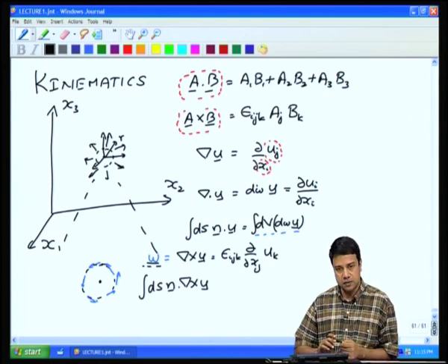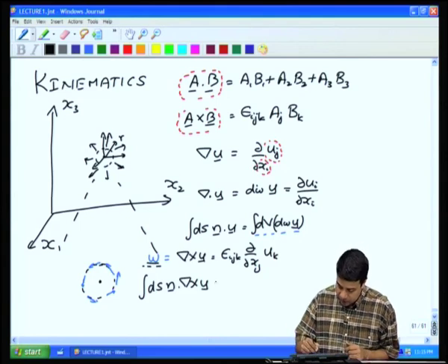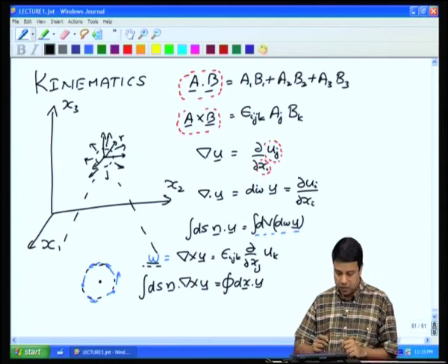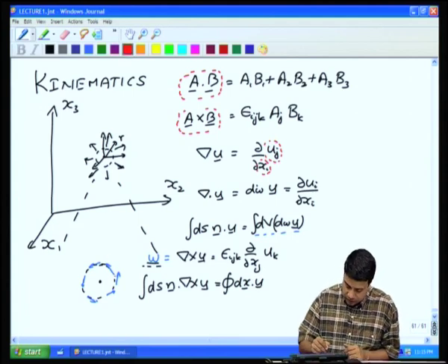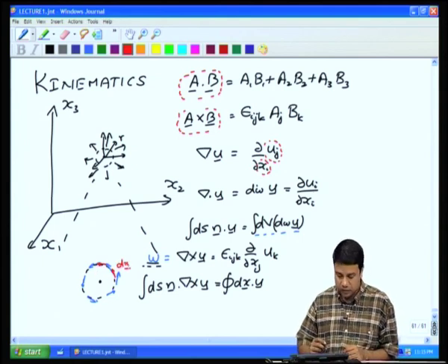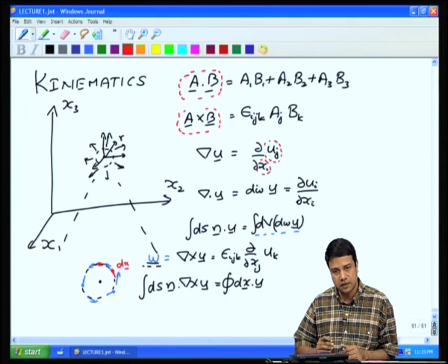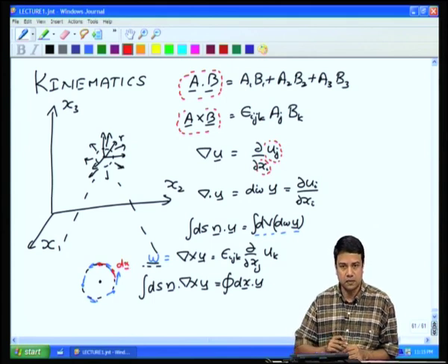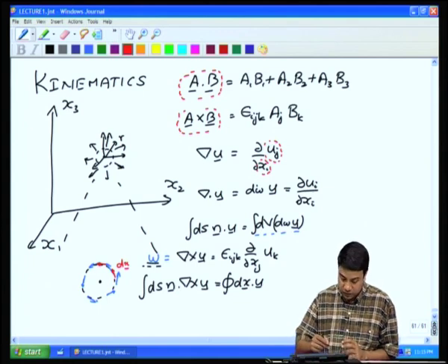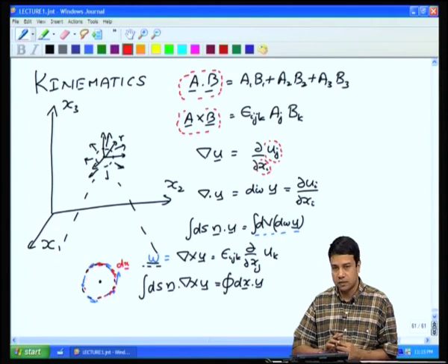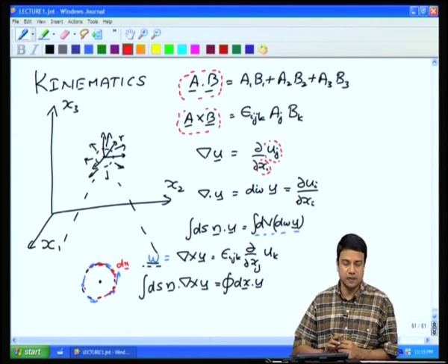and this integral of the unit normal dotted with del cross u over any surface is equal to the line integral of dx dot u. So, I take this little differential element on the surface, that is dx vector, and dot it with the velocity vector at each point, and then take the integral over the entire contour. That is equal to n dot del cross u over any surface for which this contour is the perimeter. Okay. So, those are the physical representations.